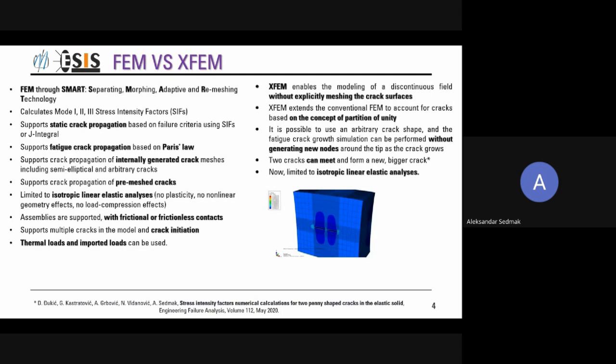Here are some comparisons, not going into details, just let me say that this smart technology is part of the classical FEM, contrary to the so-called XFEM. XFEM is extended finite element method, which has the big advantage that the mesh does not need remeshing.